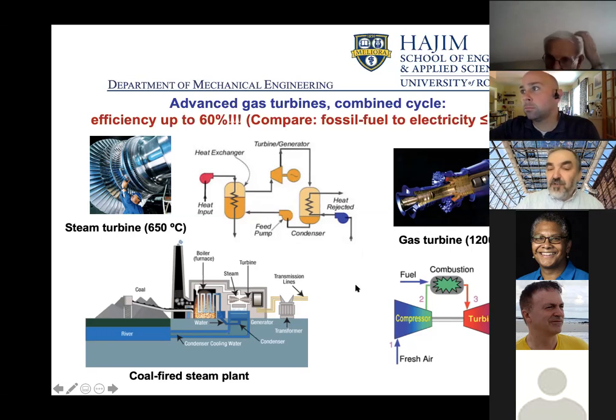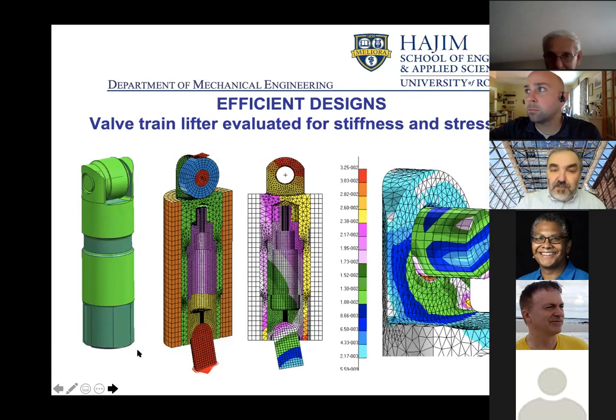Of course, in order to actually do that, I must make sure that I can design materials that can withstand temperatures up to 1200 degrees Celsius. Again, just to put this in perspective, at 1200 degrees Celsius, aluminum is melted. Aluminum cannot be used as a working material for making a gas turbine. Therefore, I have to think about the development of high temperature materials that can operate at very high temperatures without failing, essentially. I will give here one example of what I refer to as a virtual design.